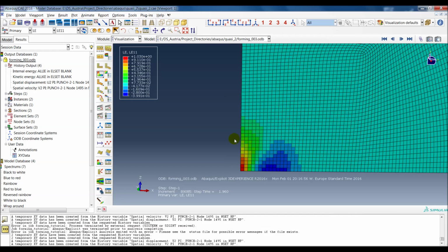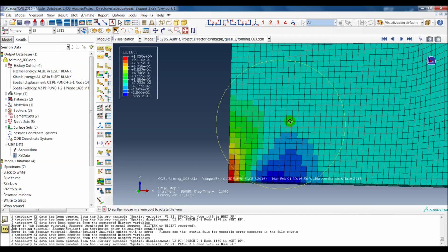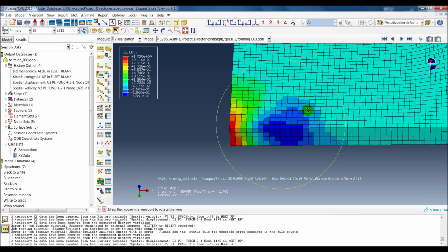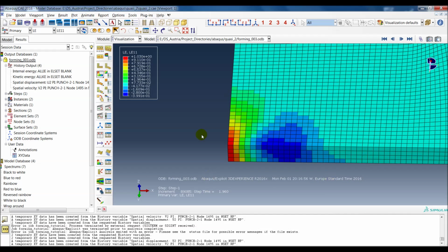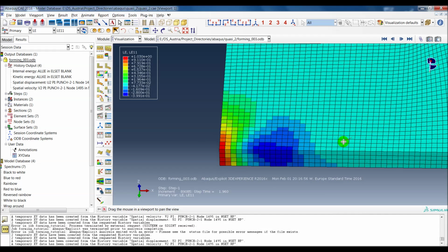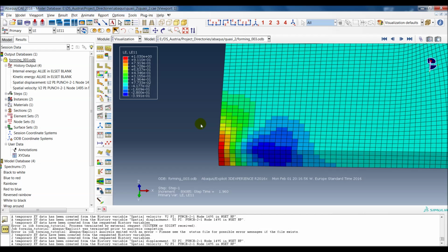However, there are perhaps some ways in which we could improve the analysis to get closer results, such as changing to quadratic elements perhaps. However, it's quite difficult to match the exact same result as the experiment, since the 12 millimeter displacement that we applied in this case, in the experiment, the plate cracked at 12 millimeters.